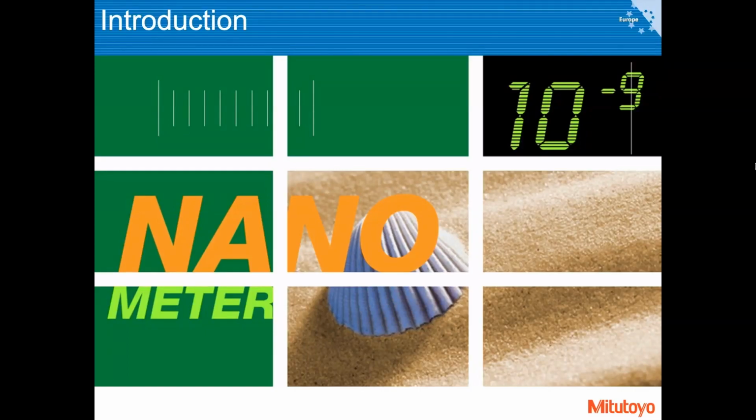In the previous subject topics we discussed, the millimeter was the default value, so if someone wrote down 15, you without reconsidering should already know that it was meant as 15 millimeters, because the millimeter is the default value in dimension metrology until it gets to roughness measurements. So when we get to roughness, we are dealing with micrometers and nanometers.